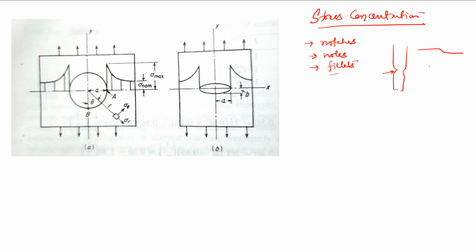And in normal building materials, suppose this is a kind of structure, some steel which is used, then it has got some fillet, some radius. So here also there will be some stress concentration, and this stress concentration will be slightly lower than at these sharp edges. So that also will help us understand why sharp edge design is not done nowadays, because that actually increases the amount of stress in that area and that may lead to failure.